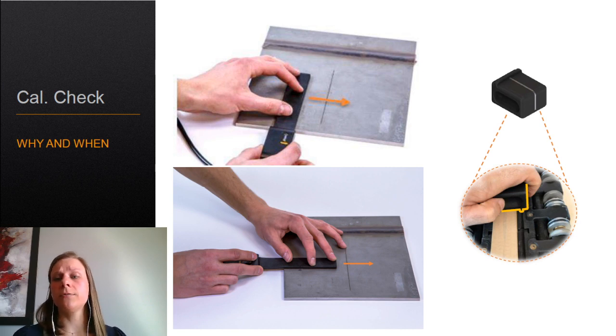What we see on the right of this slide is the spine probe. The spine probe has a coverage of 8 inches. So if you want to have a sample for that, it means a really big sample and a very long notch. So it's expensive to get and it's not always fun to travel with that in the field under the rain. So we developed a small tool. It's an aluminum reference that you just need to move across the array. It provides a signal and we can do a functionality and uniformity check with that. So the CalCheck will work for both types of reference signal. And I'm showing that on the screen, but it could be something else depending on the situation in the application.